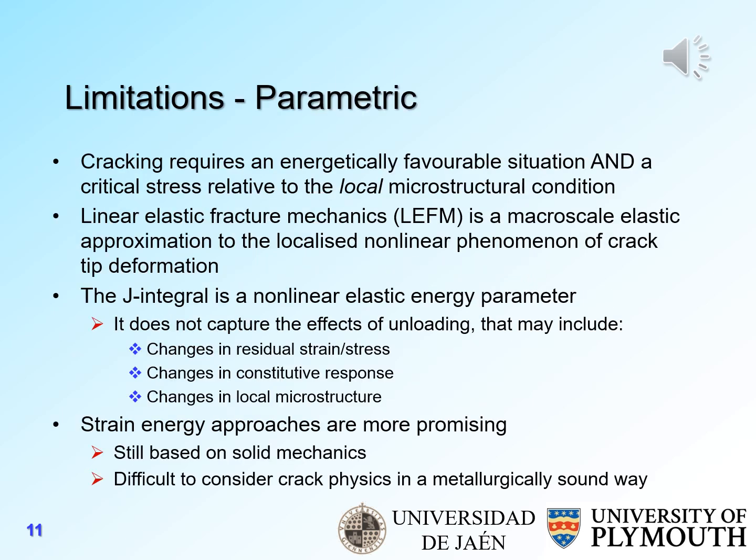One of the issues in our lack of understanding, in my view, is that cracking requires an energetically favourable situation and a critical stress relative to the local microstructural condition. And linear elastic fracture mechanics is a macroscale elastic approximation to the localized, non-linear phenomenon of crack tip deformation. So it's not going to work that well, under certain conditions at least.